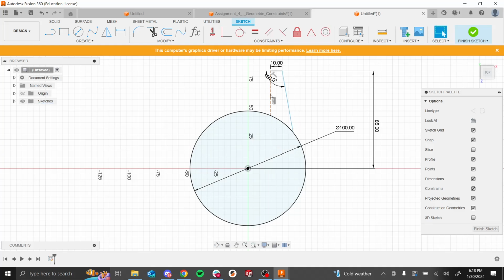So I'm going to constrain this construction line to be, I believe, coincident with this. Yeah, the coincident tool will work even if the two parts are not touching each other physically. You saw how I made this line and the center of the circle coincident. If I drew a longer imaginary line, it would go through this point, right? It's not in the sketch, but Fusion will do that, which is cool. Is everyone up to this point? Yeah? All right.